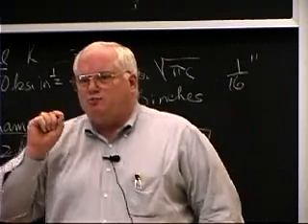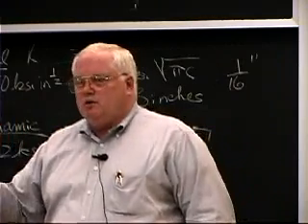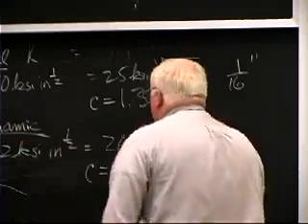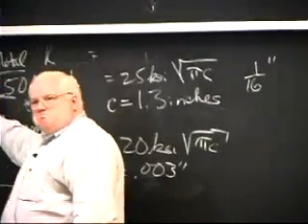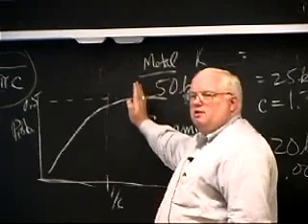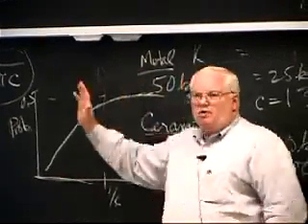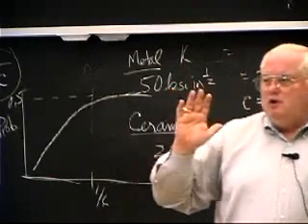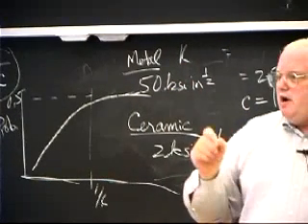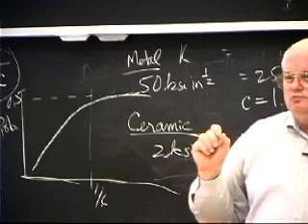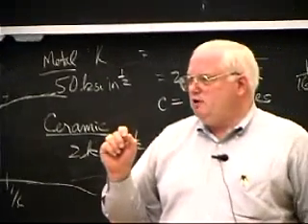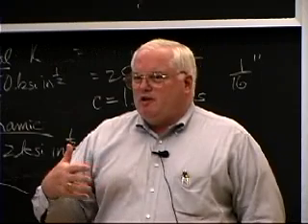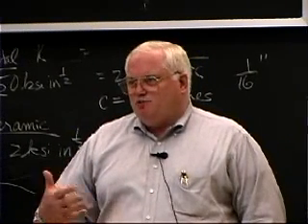And if you go to most of the welding codes, the structural welding code or the ASME boiler and pressure vessel code, they're looking for 1/8 inch defects. Why? Because they know that if they throw a sample or 10 samples at 5 different inspectors, the odds are a number of those inspectors will find the 1/8 inch flaws. About half of them will find the 1/8 inch and bigger flaws. So you have a reasonable reliability, but it's only about a 50% reliability of finding it. That's the important thing to remember.